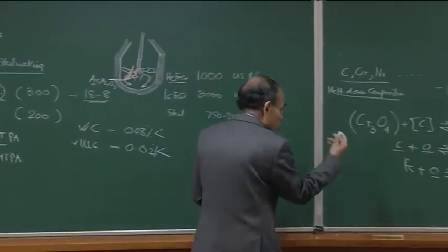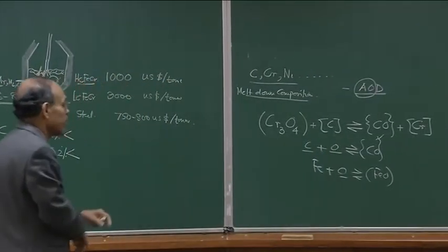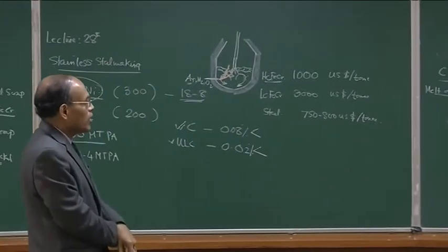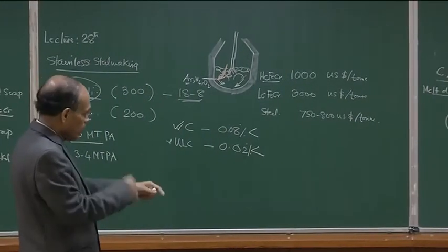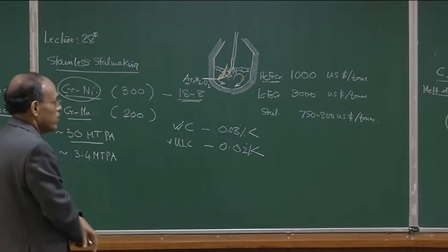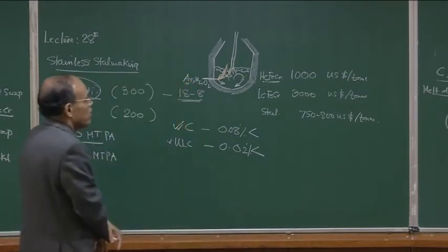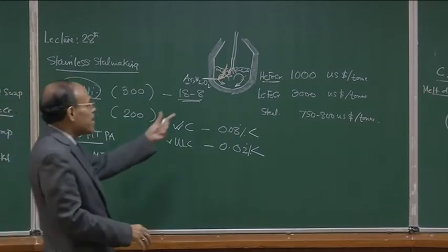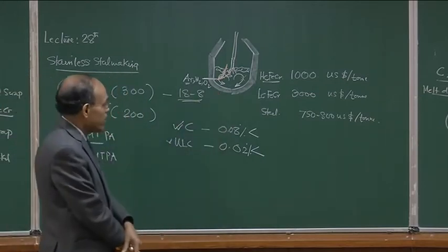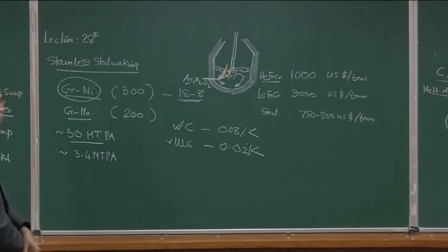These reactions are heterogeneous chemical reactions, and as we know, they are going to be dependent on interfacial area as well as the prevalent velocity fields, and that is why the efficiency of steel making is not as high as it is in the case of BOF steel making or Q-BOP process.